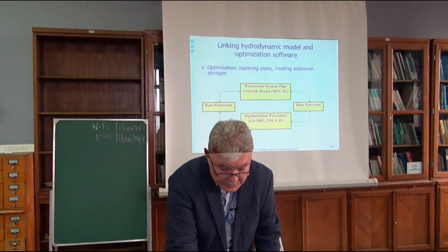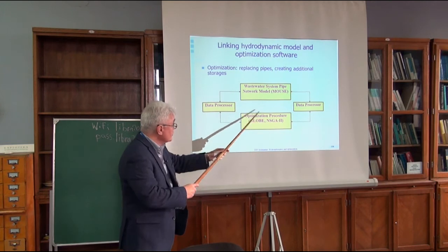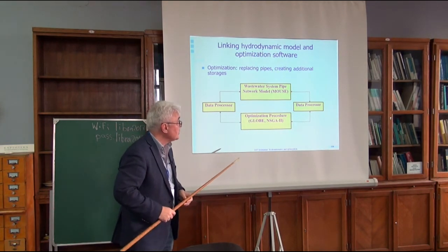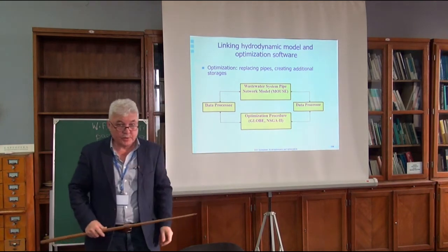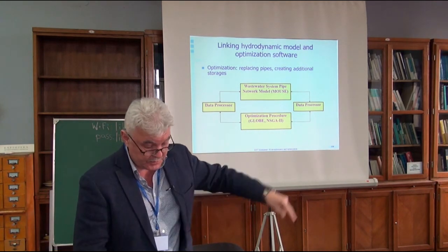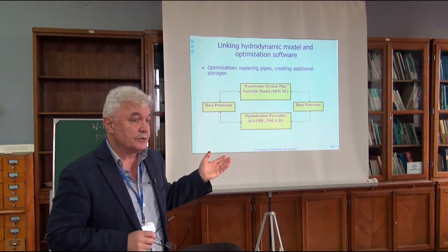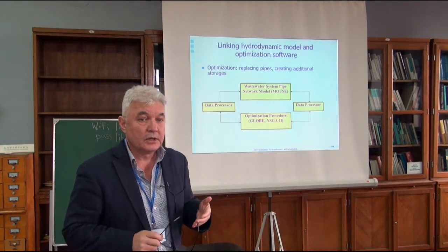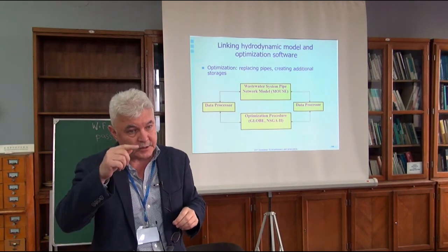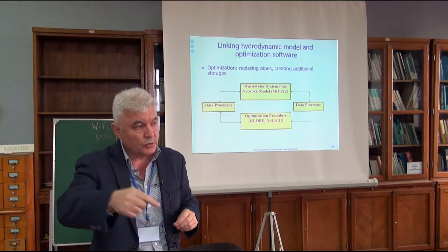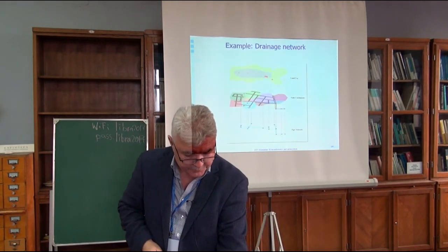Often it's not easy. Same thing we do, same optimization loop. We run the optimization procedure, and we run the wastewater system or drainage pipes model, MOUSE or SWMM or any other model. Again, it's model-based. In our research, we also use metamodels, because to run SWMM for a large network takes a lot of time. So we could run it offline, and then gradually we retrain a neural network as we get more data. So we developed this more Prism algorithm that does it.